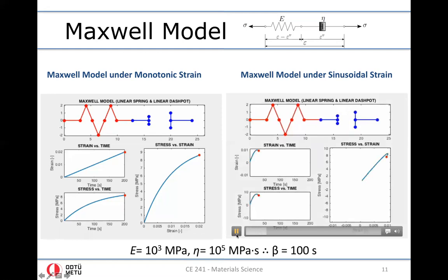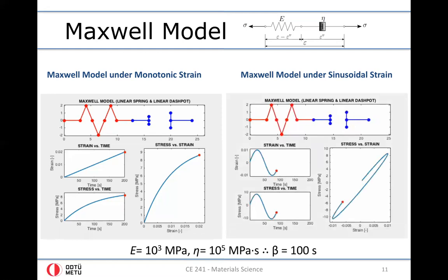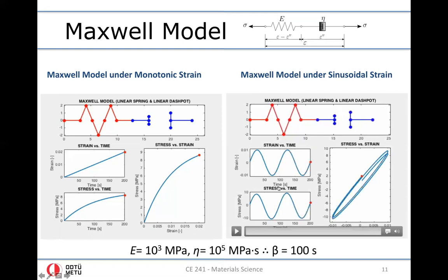Another interesting simulation is the cyclic simulation through a sinusoidal strain as a function of time. We have this strain that is applied through a sinusoidal function whose period is 100 seconds. And we apply 2 cycles, and this is the corresponding strain stress time diagram, and this is the stress strain diagram.